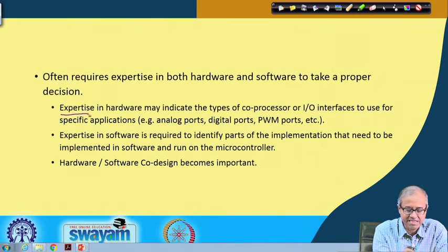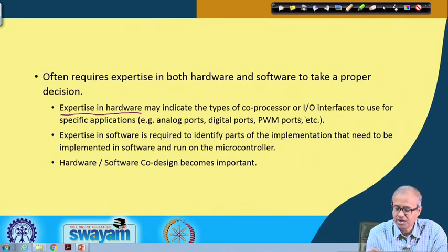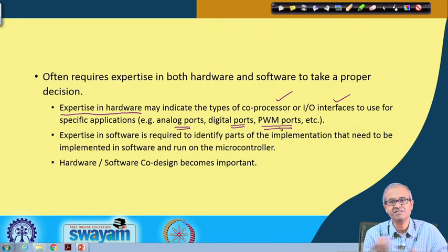Now, you may need expertise in hardware to identify what kind of coprocessors or I/O interfaces you will be requiring for certain applications, because you may have several choices. There can be some analog ports, digital ports, pulse width modulation ports, but which of them will be best for a certain application? So, unless you are a hardware expert, you really cannot take a good decision here. Okay?